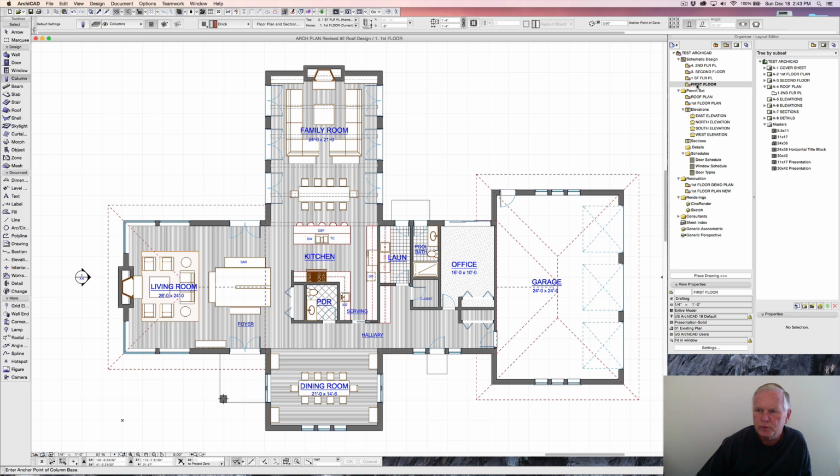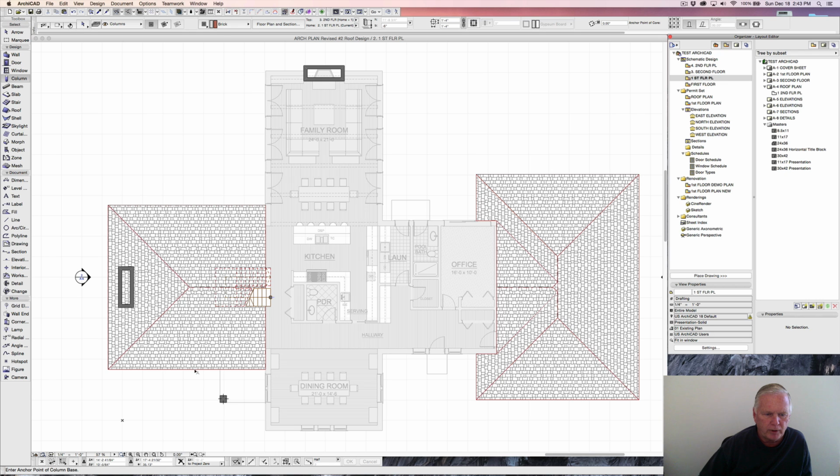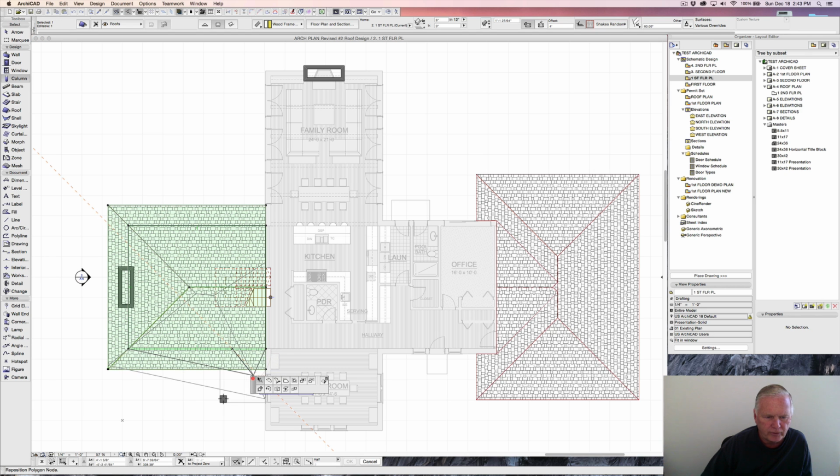Now we'll go up 1 story, go over to Organizer here, click on first floor plate, and we'll highlight our roof. And we're going to add, at our pivot line here, a node, or a handle as I call them, and put that, I'm holding the shift key down so I stay on that line, and I want to have it equal to the outside of this column. And then we're going to take this pivot line and extend the entire line. You kind of see our roof structure going with us at the moment. And out we go to the end of that column.